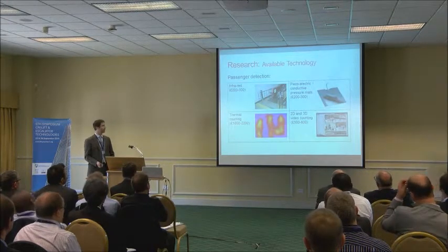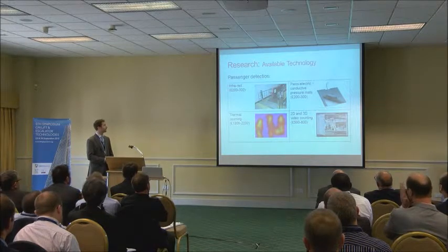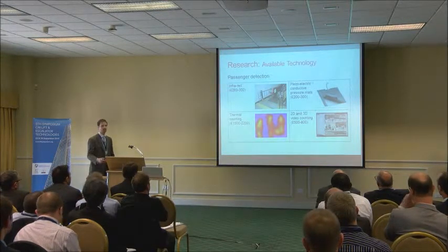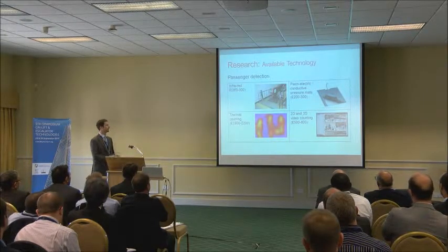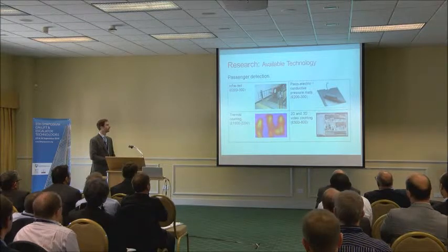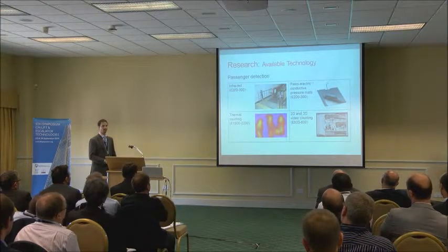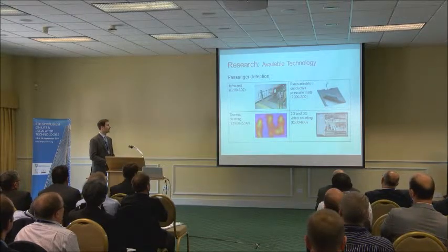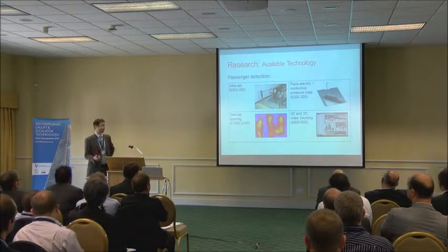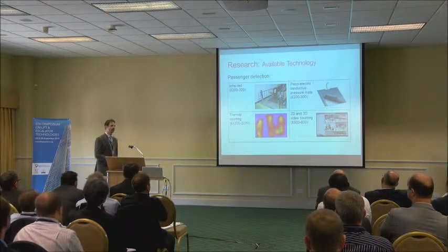And to actually detect passengers, the most cost-effective way is to put in infrared detection, and this will tell you whether or not there's a passenger there. If you're willing to put a bit more investment into it, you can get video counting as well. So this gives you the advantage of actually knowing how many passengers are coming through the escalator, which is very useful for making strategic decisions based on how many passengers you're going to be affecting.